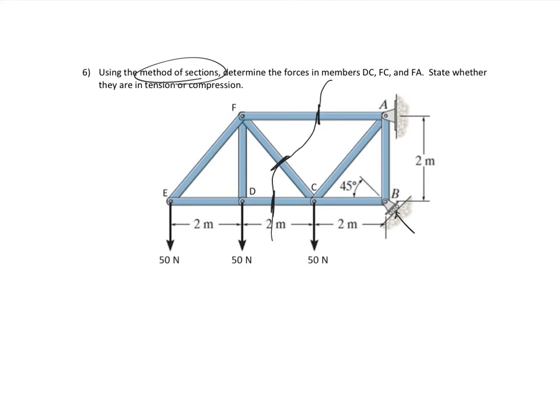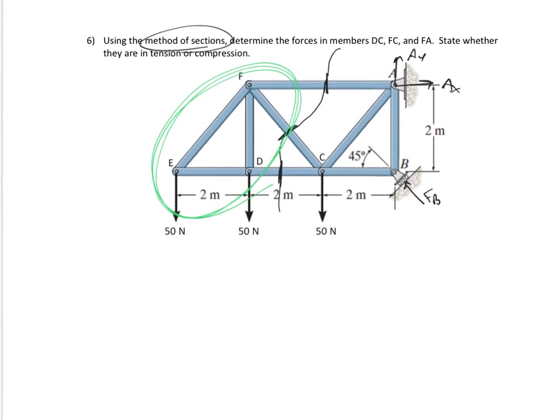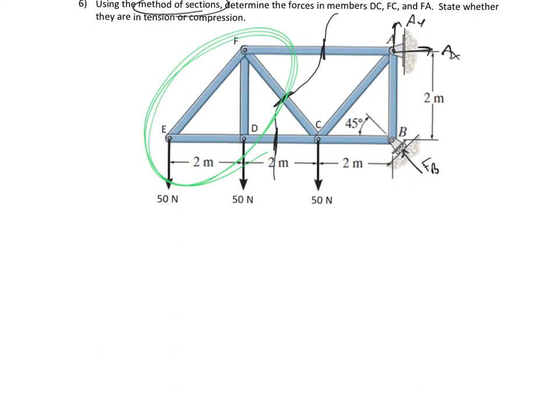I could calculate the force in B right here and AX and AY if I need to, but looking here, I can just look at the left side of it. And I don't have any reaction forces, so that's what I'm going to do. I'm just going to look at the left side of it, and the ones that I cut through, I expose those forces.